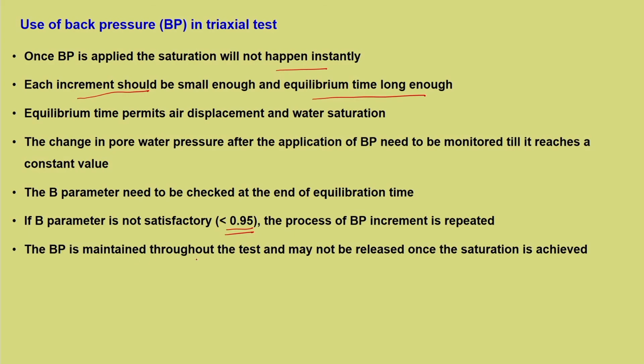The back pressure is maintained throughout the test and may not be released once the saturation is achieved. So, this is another important point, once the back pressure is applied, it is kept as it is. Once the B value is achieved, it is not that we close it. So, this back pressure would remain in the soil sample till the test is completed. So, back pressure is more like a static pore water pressure. We have seen what is a static pore water pressure.